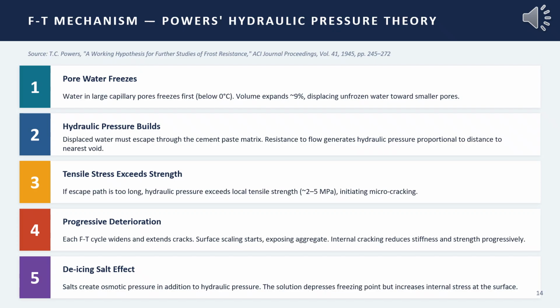Step 5. De-icing salts compound the damage through an additional osmotic pressure mechanism. When a saline solution is in contact with pure ice or dilute solution in the concrete pores, osmotic pressure drives water movement. This movement generally is towards the higher concentration gradient. This adds another layer of internal stress on top of the hydraulic pressure.